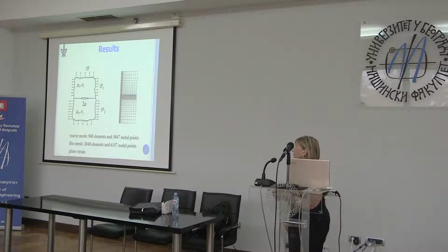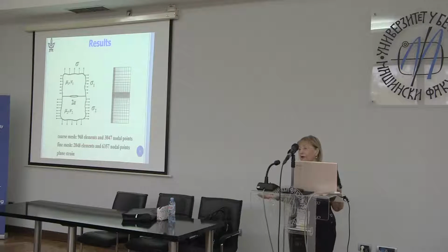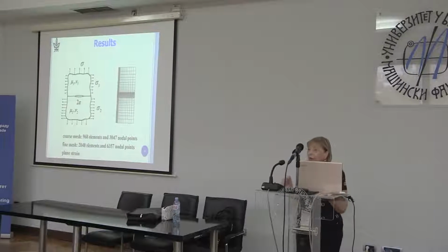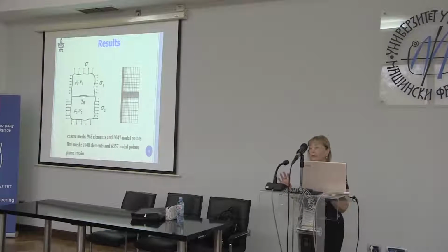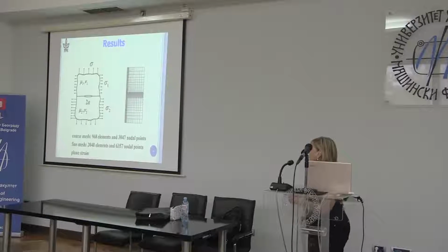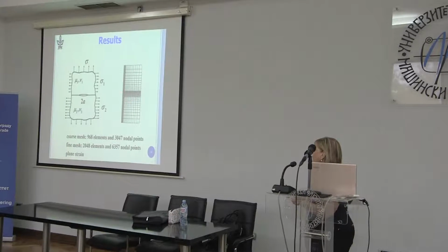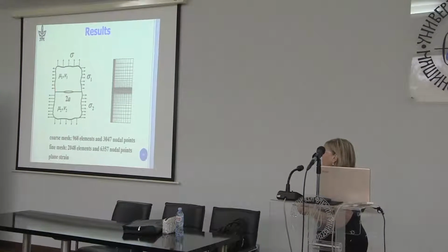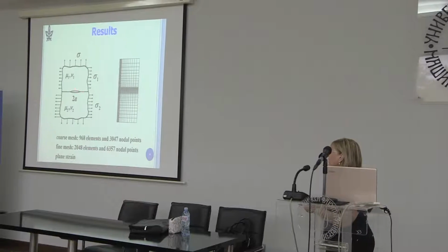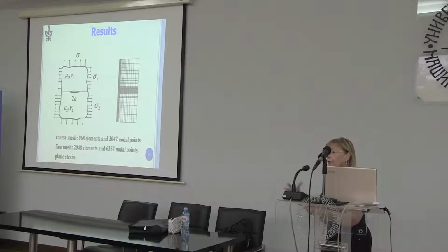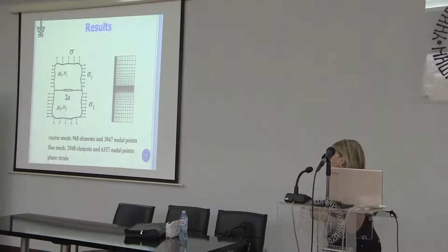And we considered a very large body. In finite elements you can't analyze an infinite body. Actually you can, there are infinite elements, but you can use a finite body, and if the half width and the height are 40 times the crack length, you approach an infinite body.